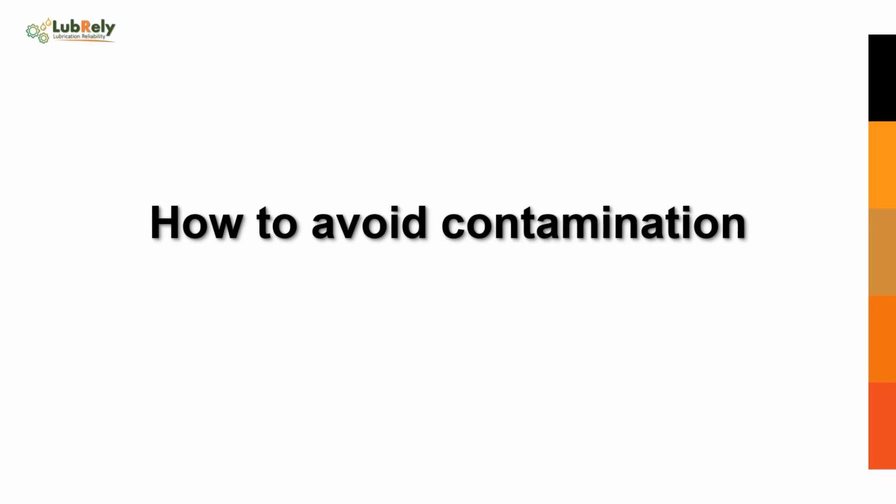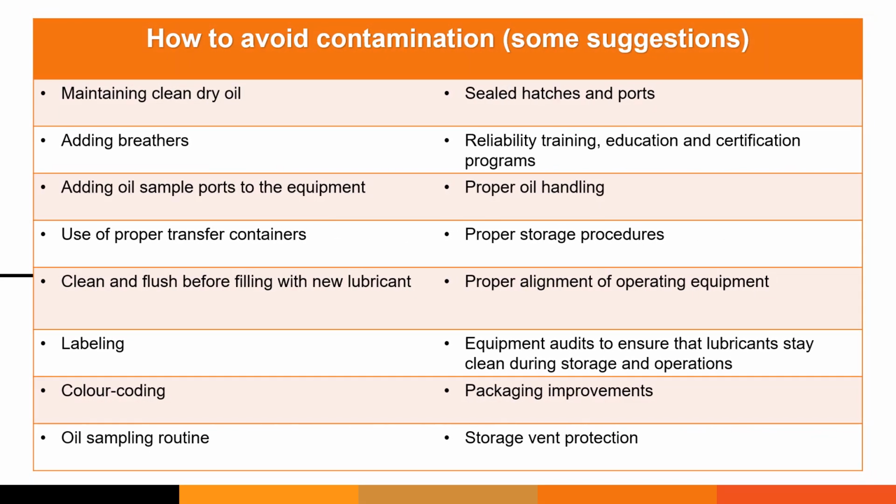Avoiding contamination. Contamination can be minimized, or even avoided through maintaining clean dry oil, adding breathers, adding oil sample ports to the equipment, and many more reasons. See for yourself.